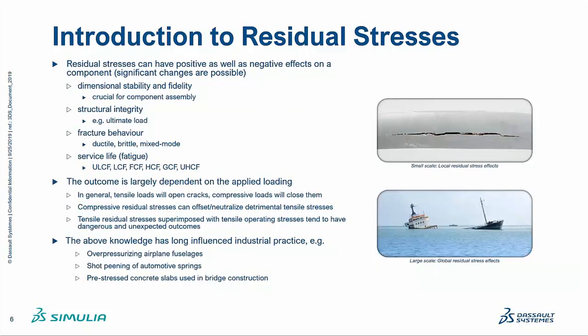There are both positive and negative effects that residual stresses can have. It depends on what you do. On matters such as dimensional stability and fidelity, which is crucial for component assembly, you can picture it as such that if a component doesn't fit, or if you have large residual stresses and you have to bend it in some direction, then you might actually break it when you try to mount it to something. Anything involving structural integrity, fracture behavior, or, chief among all, is the service life in terms of fatigue. Because this is where the residual stresses actually come into play.